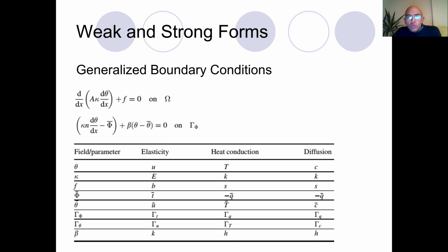Certainly you can use generalized boundary conditions. So how can we define the generalized boundary conditions? Now we want to implement the boundary conditions, and remember that after choosing the trial and weight function, the weight function has to be 0 on the prescribed boundaries, the Dirichlet boundaries.